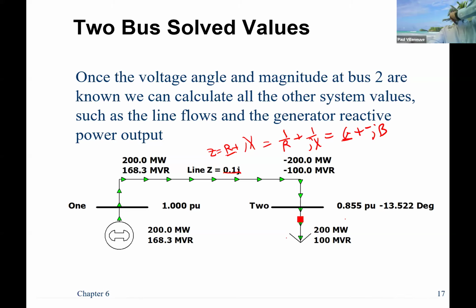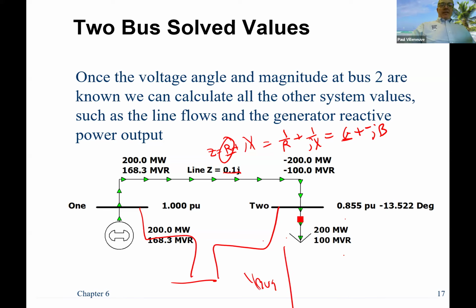Now, if we have 3 buses, we have 2 lines. No, you could have more than 2 lines, you could have 3 lines, because if I put another bus down here, I could run lines here and here, right? I could have 3 lines. Which one, we have 3 Gs, right? You could have 3 Gs, yeah. Which one are we looking at checking? So keep in mind, the G is only determined by the real part of the impedance of the transmission line between the 2 buses. That's not the G, but the Y bus that you have to build. Your Y bus would have to be a 3x3, right? You'd have an element here, here, here. So you'd have to build the Y bus the whole way through.